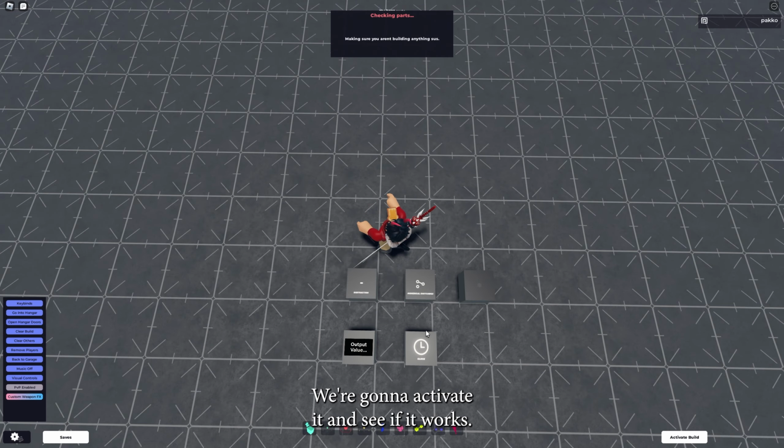We'll make our moving height 1 just for testing purposes. And now we do the same thing for our arms. We'll also make our animation speed 1. And later on, if we're not satisfied with the speed, we can change the animation speed to however fast we want. Before we get to our equations, add a multiplication block under the animation speed, and connect the animation speed to the multiplication block. After that, connect the subtraction output from the clock circuit into the multiplication block.